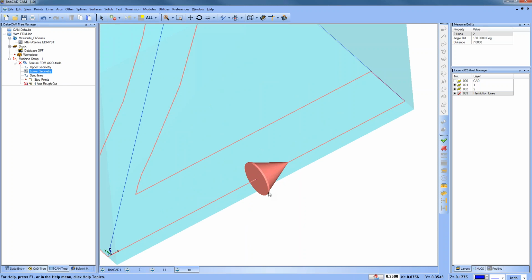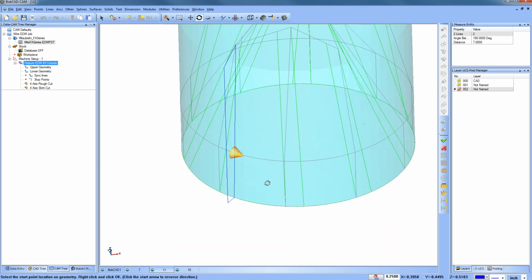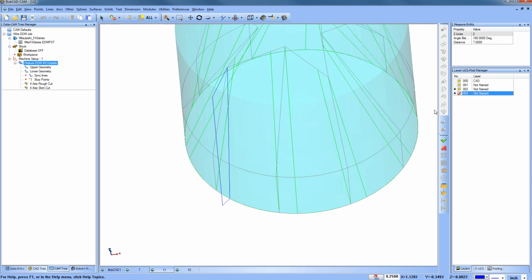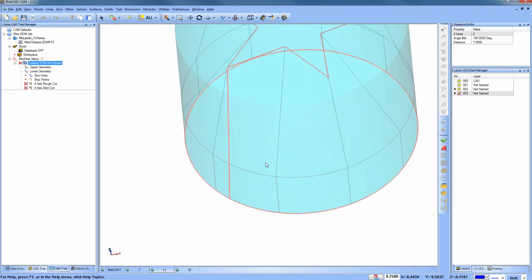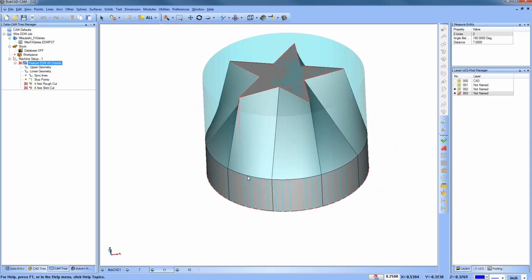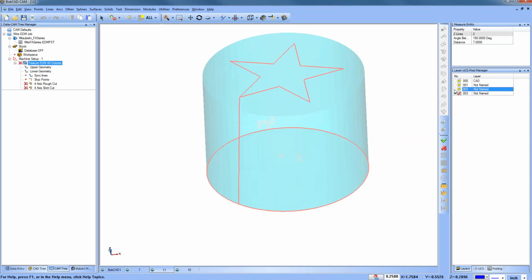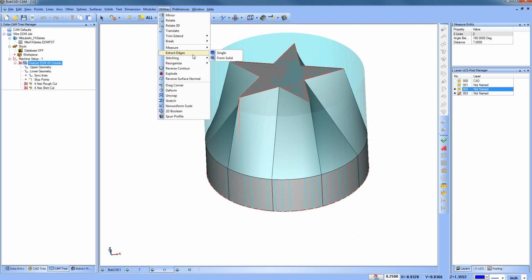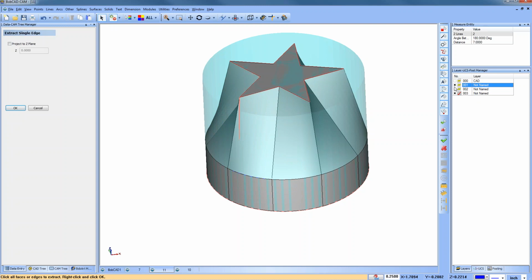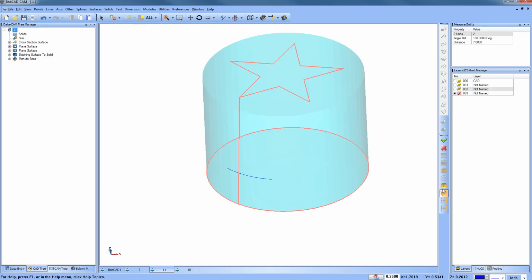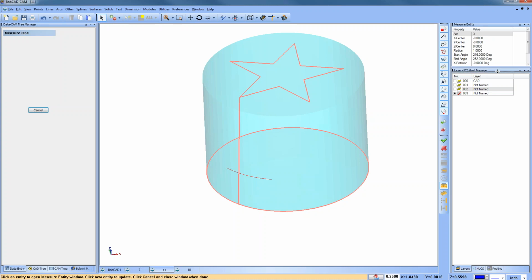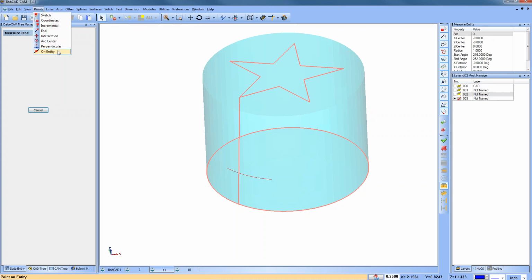I'm not certain. Could be a spline curve on the bottom. That is a good answer as well. Let's take a look at that. So let's blank this stuff out here. This is a surface edge, you know. So what we're going to do is we'll convert that geometry. Okay, and then we can measure this, and it is an arc is what it is. So you would get 0.4590 on an arc. Try off of the arc on the 2.